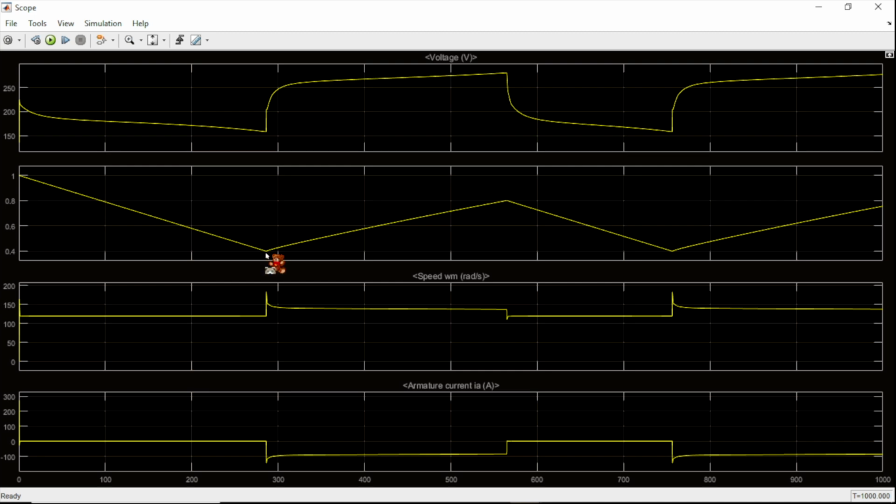A mechanical torque, that is the minus 200 Newton meter, is applied to the machine so that it acts as a generator and provides a current of 100. So here you can see this is the 100 ampere current. Okay, so here you can see almost 560 or 80, the SOC is 80%. At that time the minus 200 Newton meter torque is removed and the load is connected, that is the minus 50. Okay, so here you can see, and this process is continuous.